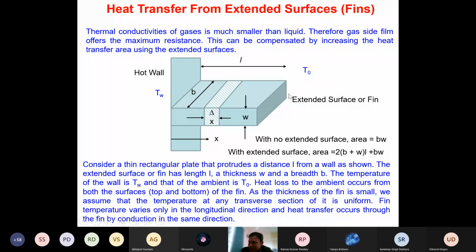That should be the ideal design for me, if all the heat conducted is getting dissipated from this large surface till this end. That's what I'm desiring. Then I can even design a triangular fin like this, isn't it? I don't need this surface area additionally, because this surface area will not be significant compared to the upper surface area or the bottom surface area. Do you all agree?